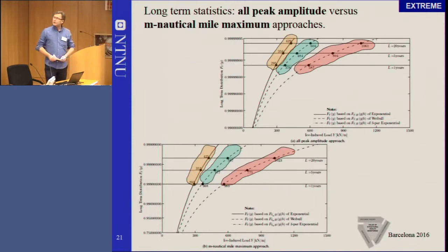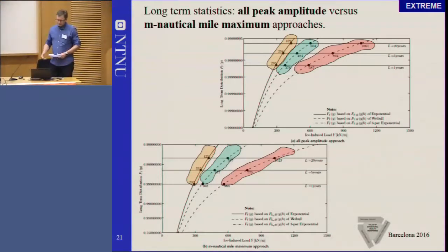So we see that there is a significant under-prediction by using the other models, so that means knowing that you have an improved statistical fitting gives you more accurate prediction of the extreme values, loads which will act on this hull. This hull is robust, but the system is intended for other types of vessels like tankers traveling in ice. That means you will have different ice classification. This is an icebreaker, so it has a very high ice class, but you have also other vessels, merchant vessels with lower ice class. So of course to predict the extreme ice loads would be important to avoid damage to the hull and also failure and leakage.